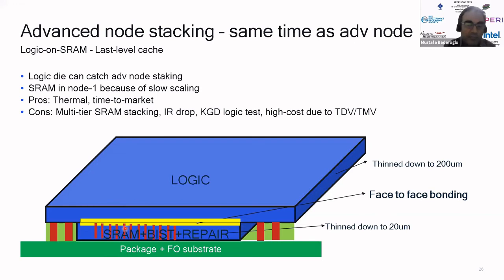I'm sorry for my mistake here. So here, for instance, you have a 5 nanometer node or 3 nanometer node coming up. Immediately, you can focus on the logic node, release it right away, and you don't need to have any TSV technology adopted for the logic node. And the SRAM technology can be picked up from the previous node generation, like 5 nanometer nodes.